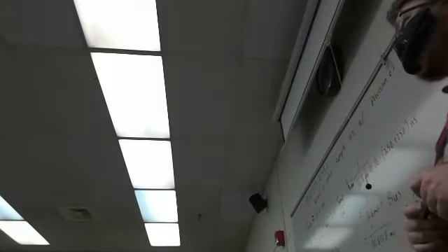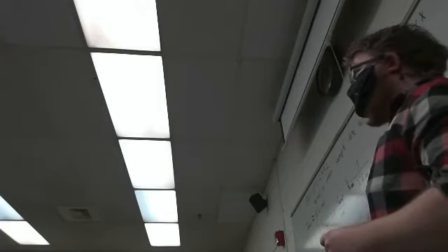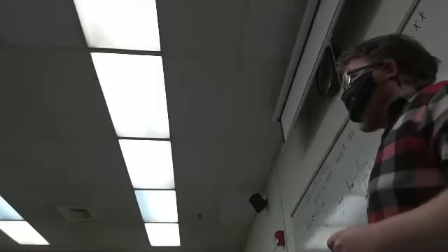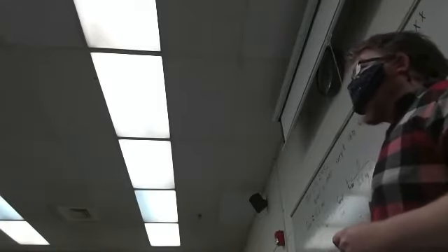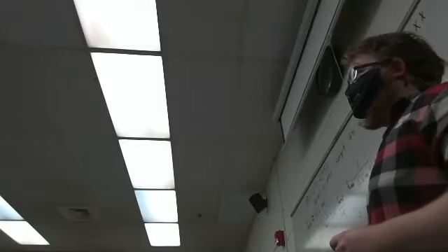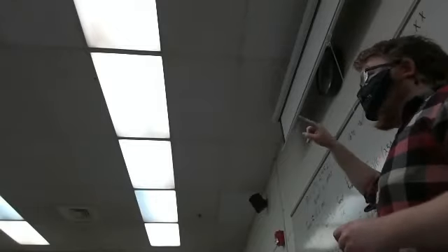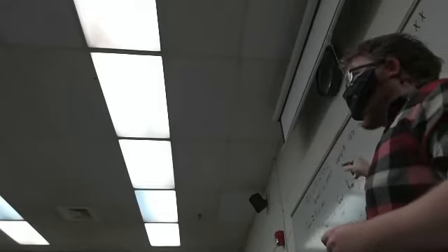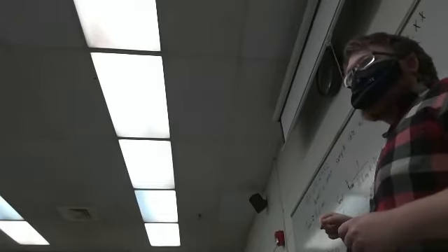Where does the 8 microseconds come from? That's the 16 times this. Oh, 8 microseconds. Okay, here's the top. So it takes me 8 microseconds to transmit out the 16 bits. It technically takes me 8 microseconds plus 200 nanoseconds because of the setup, the CS rise and low. So man, it's just shooting those numbers out, isn't it?